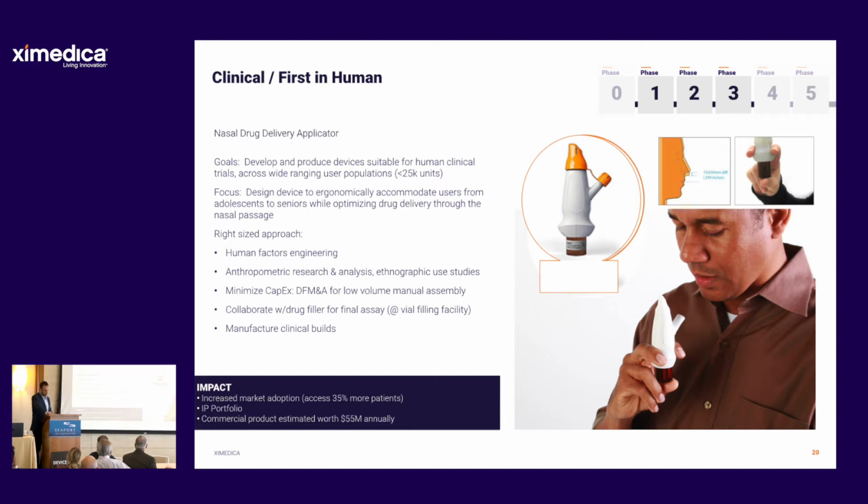We took a bifurcated approach to this. The first was to do the anthropological research on the facial geometry that we needed, particularly the relationship between the nose and the mouth. That didn't exist in literature. You don't want to reinvent the wheel, but unfortunately, that data wasn't readily available. So a big portion of the early work was to develop test methods and equipment to go out and digitally scan hundreds of patients. We then built that data somewhat in parallel.